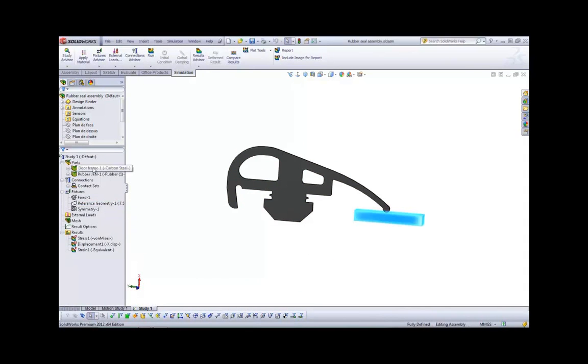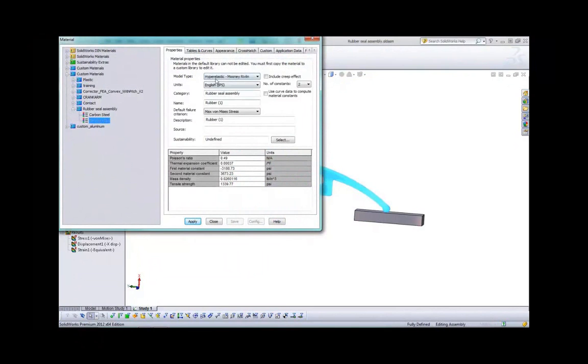To do that, again, we have materials. Again, we follow the same process over and over again. The material, let's take a look at that real quick. It's a rubber material. In our nonlinear analyses, or in our nonlinear package, we have our linear elastic isotropic material, which is the default, but we also have nonlinear elastic, some plasticity models, 3 in fact, the von Mises, Tresca, and Drucker-Prager. We also have hyperelastic material models, viscoelastic, and Nitinol models.